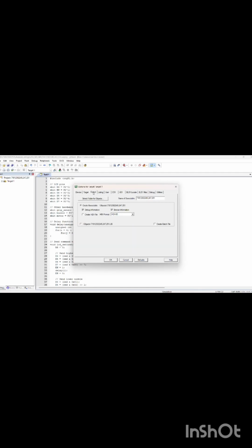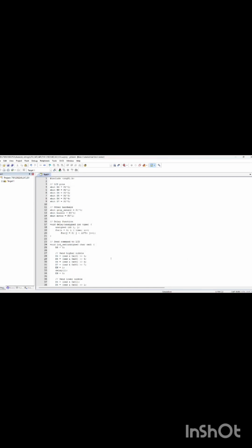Secondly, the drowsiness detection logic. The 8051 microcontroller constantly reads the signal from the IR sensor. If the microcontroller receives no signal indicating hand presence over a preset duration like 3 to 5 seconds, it considers this as drowsiness or loss of attention. Once this condition is met, the microcontroller will activate a buzzer which gives an audible alert to the driver, potentially waking them up or regaining their attention. The time delay before triggering the buzzer can be modified in the code to suit different conditions accordingly.